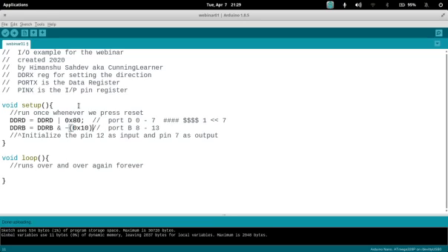This time I'm going to write 1 0. And why this is coming 1 0, let us just see. Just consider an 8-bit register again, and we are going for pin number 12, starting from 8, 9, 10, 11, 12. So I'm going to write 1 0. We can also use shifting operators, so 1 left shifted to 4. So we are done initializing our input and output.